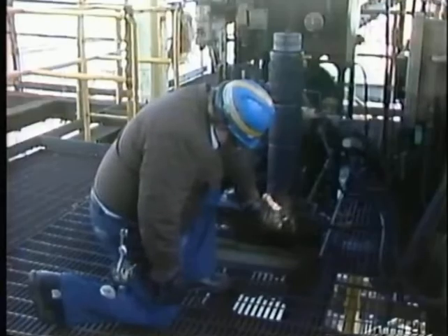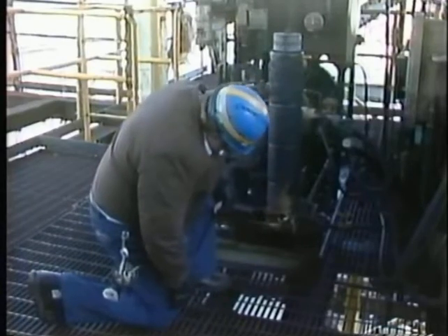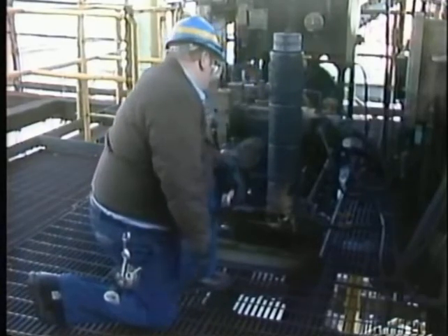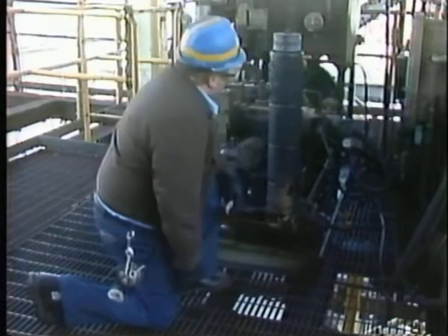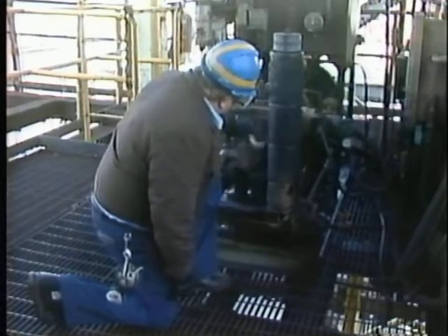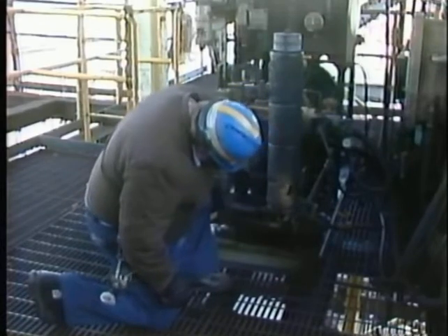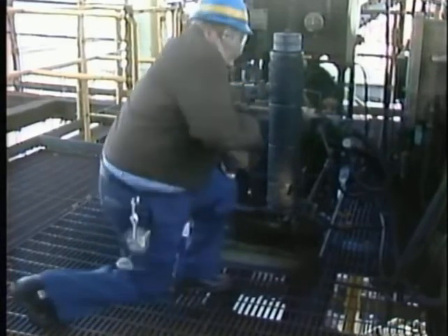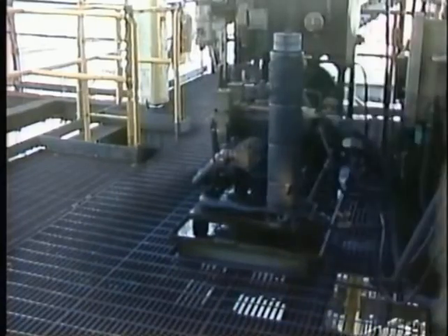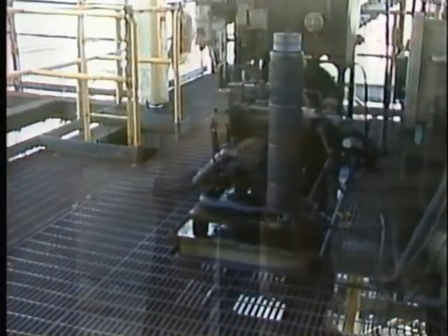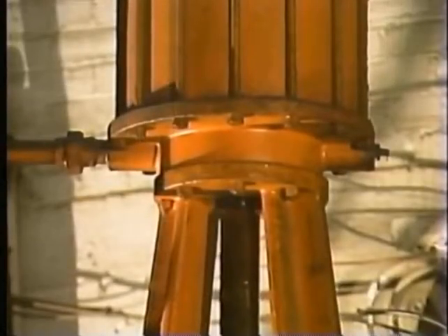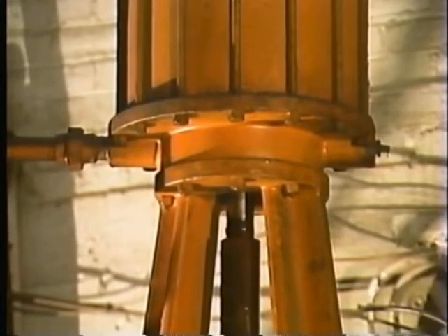The operator in this example also checks a pressure gauge that indicates the system operating pressure. Significant changes in pressure can cause problems. For instance, too high a pressure could blow seals in an actuator and cause an internal leak, resulting in erratic operation. One more thing an operator should check on a system is the actuator.